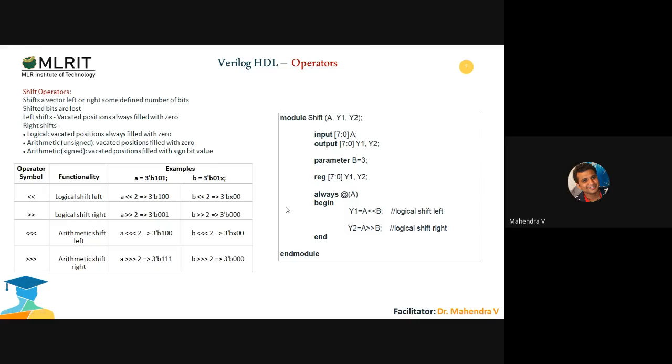Okay. Now this is how we perform it. Here you have to remember another thing. Shifting left and right can be represented by using these operators, but how many bits to be shifted left and right also should be represented. Otherwise, that shifting will happen only once and then stop. But in general, we need to shift multiple bits. For that, this is the format we can follow.